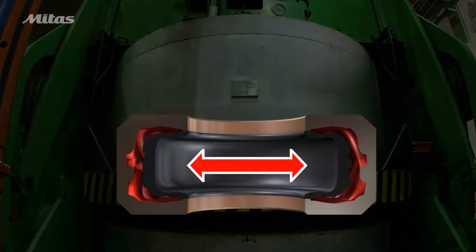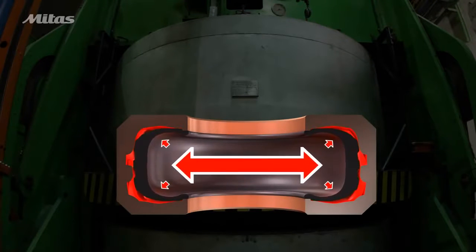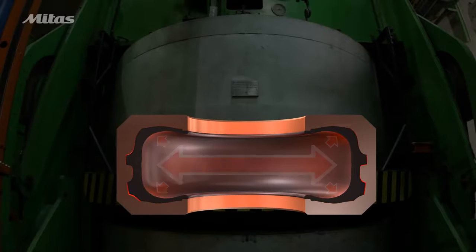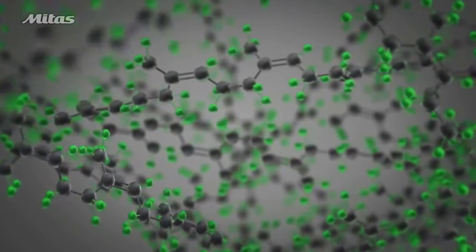The curing medium pushes the green tire into the mold. The rubber compound is heated and becomes plastic. It fills the mold. The vent system lets the excess air escape the mold so that the rubber fills the mold completely. The applied heat also initiates a process called vulcanization.